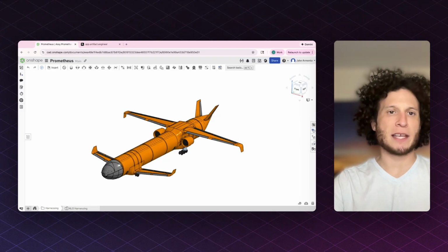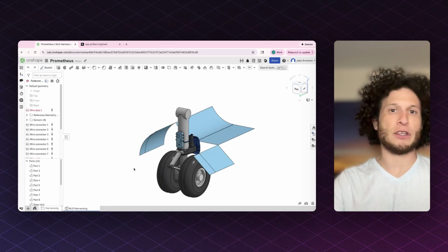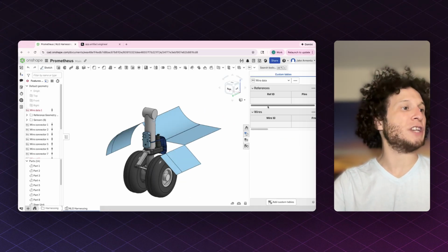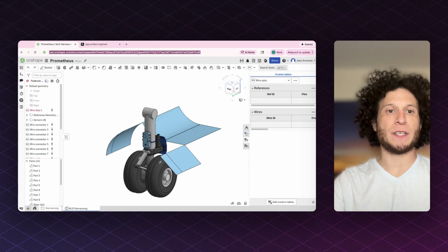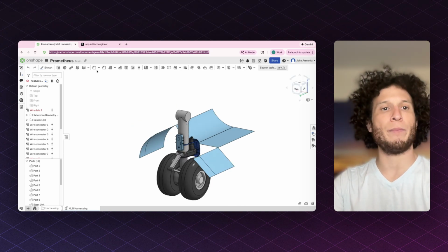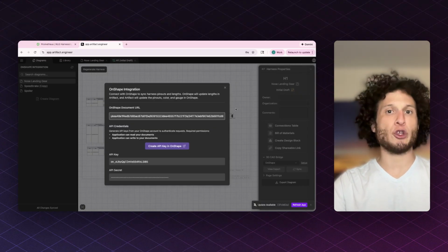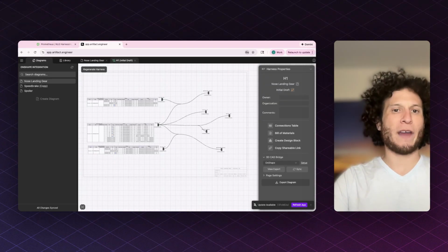Now that Artifact has access, we need to point it at the right Onshape workspace. I already have a tab with the wire data feature in it and some connectors placed, but notice how there's no actual wire data associated with the part. In Onshape, since the URL contains all of the unique document identifiers, this link is all we need for any given harness. I will simply copy this URL and paste it in Artifact. If you're going to build multiple harnesses in Onshape, you should do one workspace tab per harness and reference each one individually.